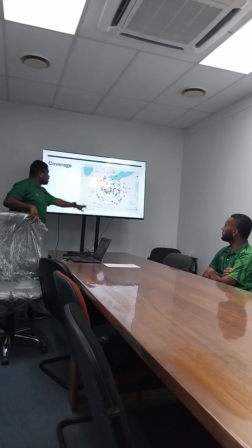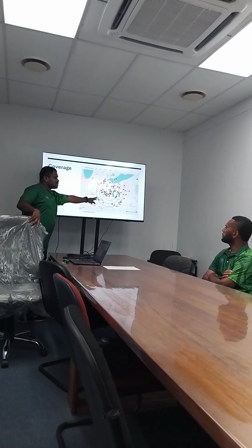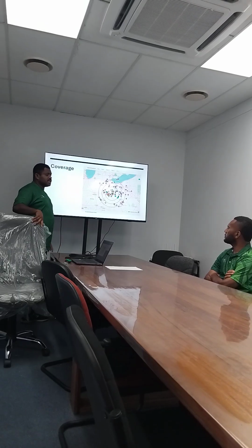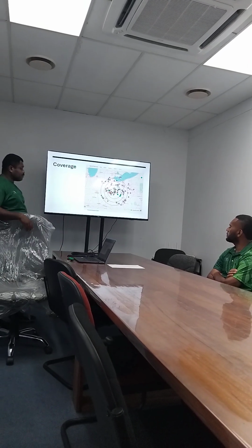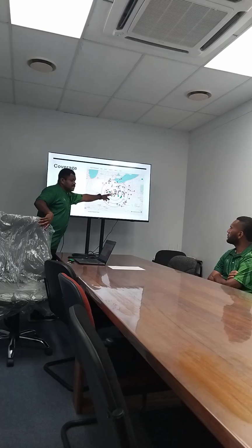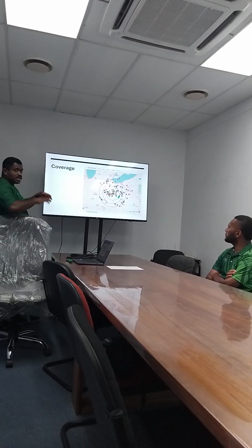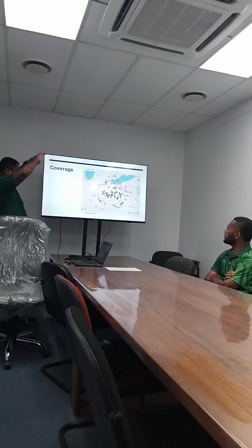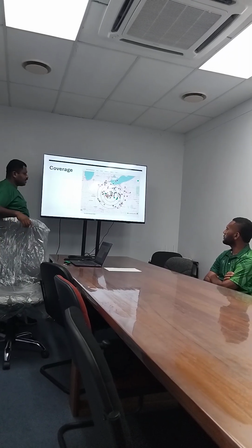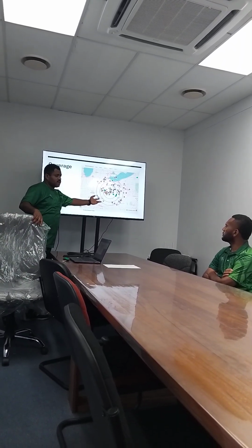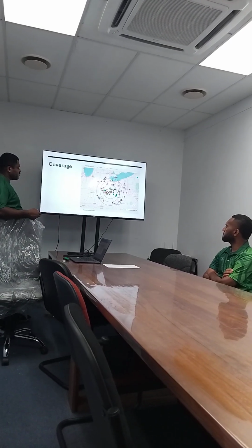You might say, oh, it's far out, it's the furthest, but it's actually picking up the ADSB data. As it comes closer, it will indicate that it's moving closer. So basically, the illustration is denoting coverage, how far out an ADSB receiver can pick up. It could be a 100 nautical mile ADSB receiver or 50 nautical mile, depending on what type of receivers you have.